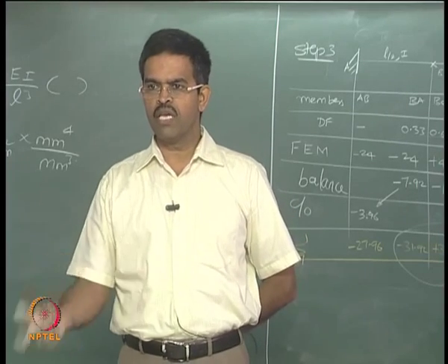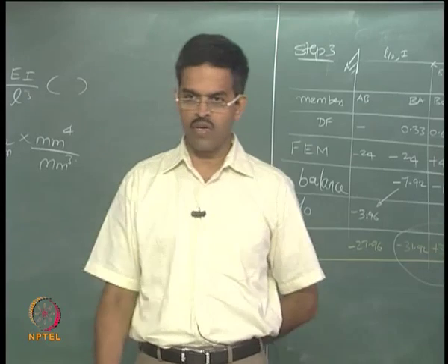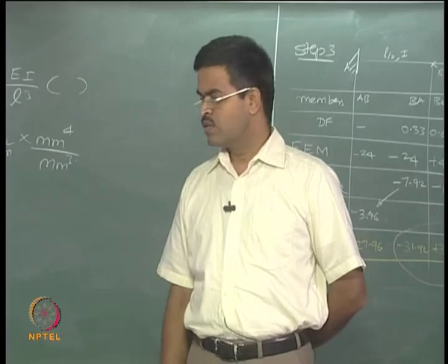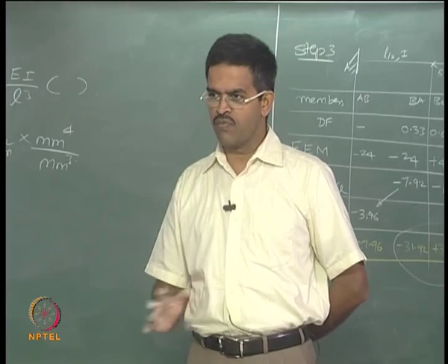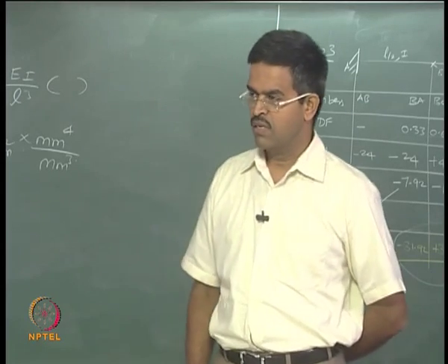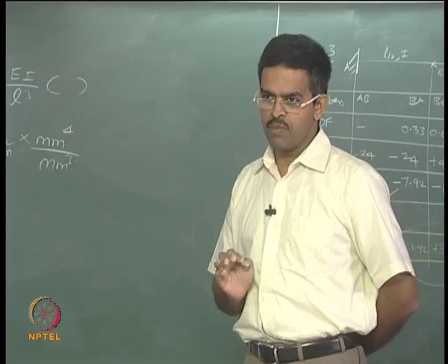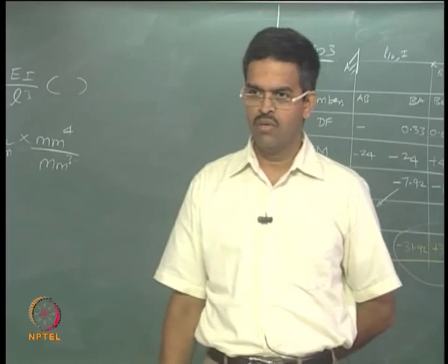Therefore, you depend on numerical analysis, where you model this in a software using a finite element mesh and let the software arrive at k and m, whatever value it gets, do the analysis and get the response values, which may be absurd, which may be even wrong also, because you have no clue how to derive them. Though in this course we will not teach you how to derive stiffness and mass matrix for buildings and structures, I am taking only very few examples because many of you may not know.